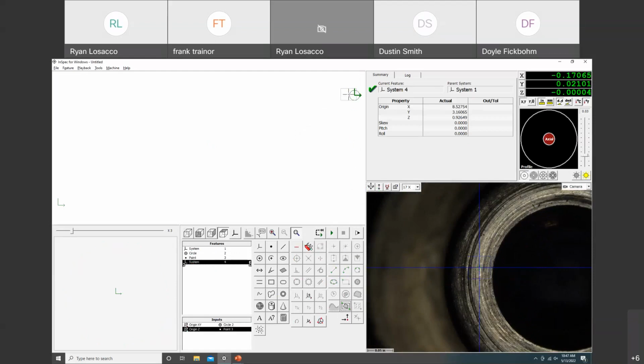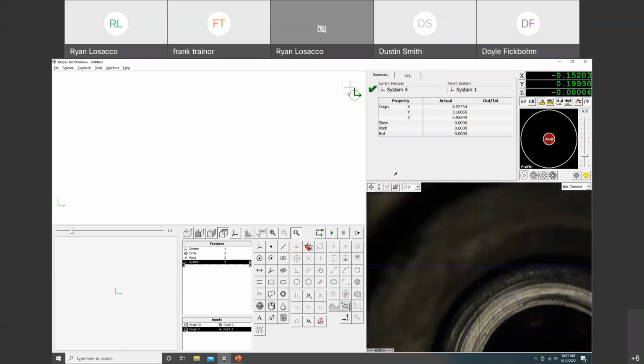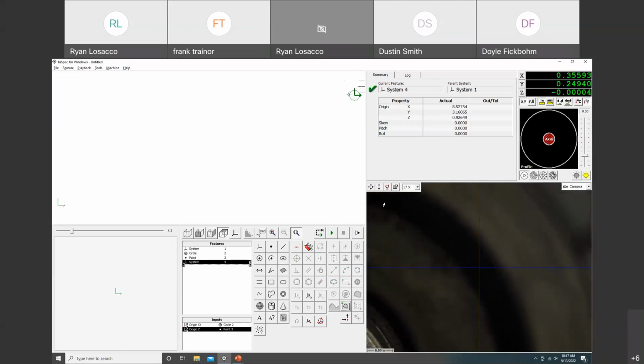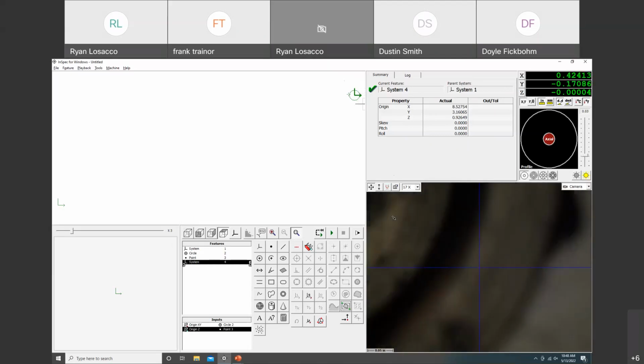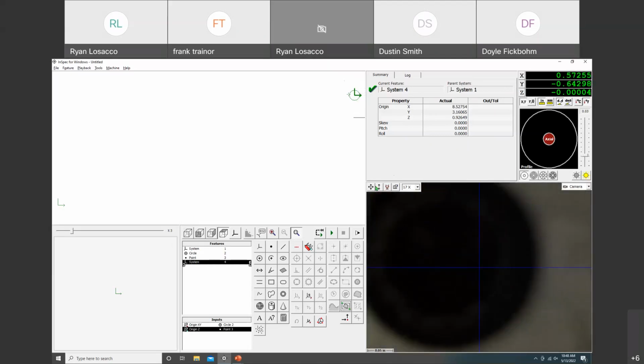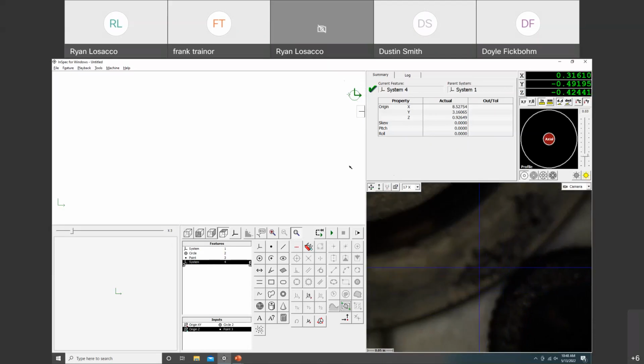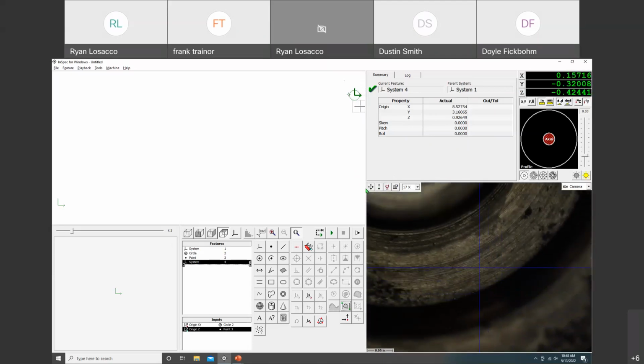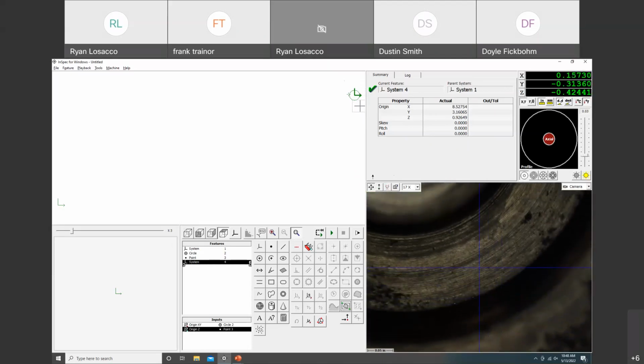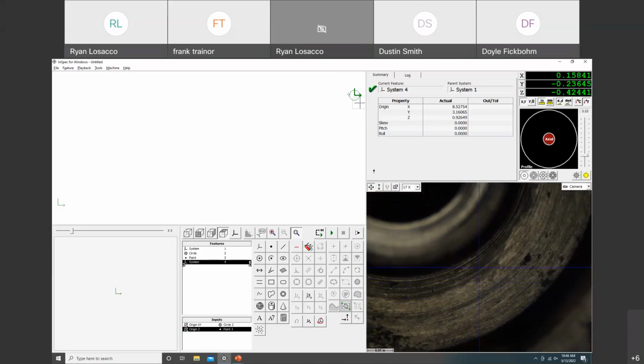And I don't need a skew because no matter how this goes on, it really doesn't matter. If you would like to, you could set a skew to the stage square or your fixture, or in this case, I have 2 bolts that go into my threaded plate that I could do a skew between the center of these 2 bolts to get a skew going on there. But if it's a part like this that the rotation doesn't matter, you're good to go there.